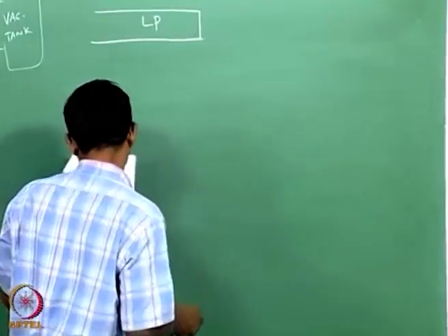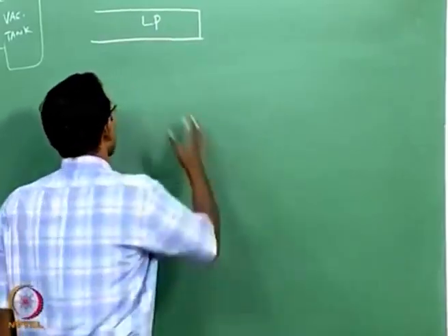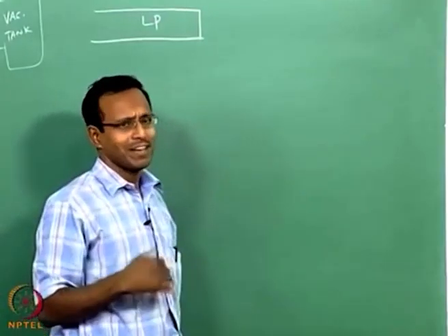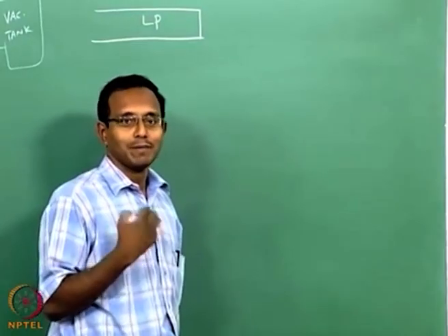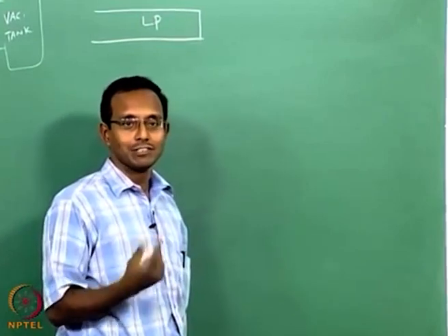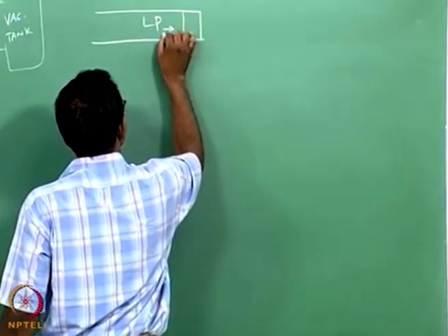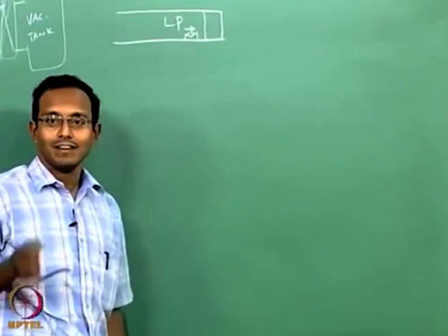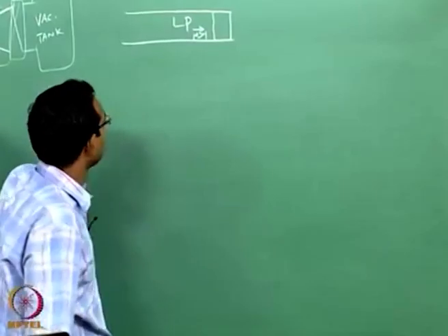Okay. Now we know that in a shock tube, when a shock is coming this way, behind it the flow is typically supersonic. Of course I can make it subsonic also, when the pressure difference P4 by P1 is not very high, then it may be subsonic flow behind it, but typically we will have a case where it is supersonic flow behind the shock. Then when the shock is coming here, flow behind it is M greater than 1 and all this flow is having exactly the same Mach number, neglecting viscosity, neglecting friction, we discussed that last time anyway.